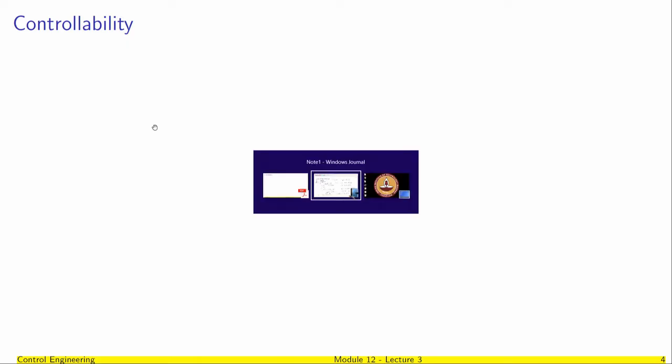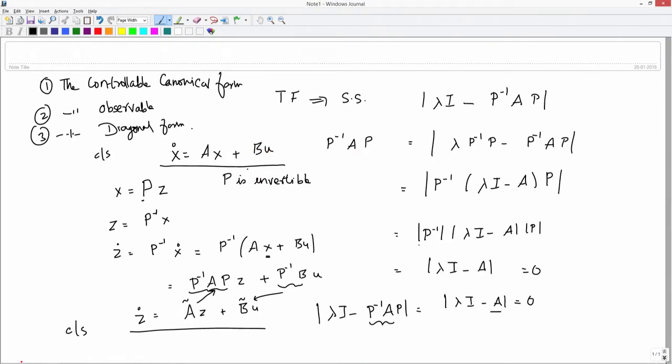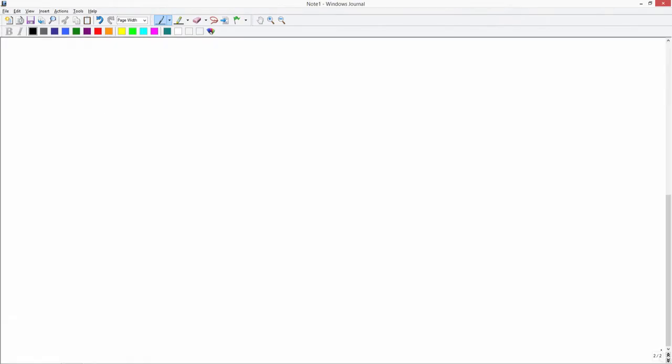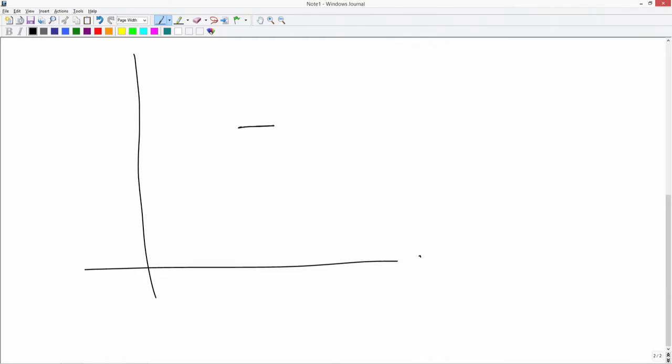Okay. So, the next thing is controllability. Let us again look at it with the help of an example. Let us say I am moving in a plane. Just for simplicity, this is just for illustration, say I have a simplified model of a car, and say all I could do is move in this direction. I can just go forward, I can go back, but steering is not allowed. So, this movement is not allowed. Now, with the application of input u in this direction, I can move forward. Application of u here, I can move backwards.